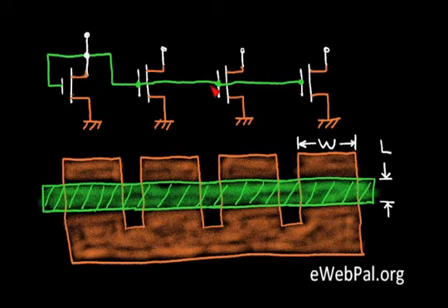So the green is the gate electrode. And let's do some connections here. On the transistor at the left, this gate electrode is connected to this orange drain region corresponding to this connection here. Now the gate runs across the next 3 transistors here.